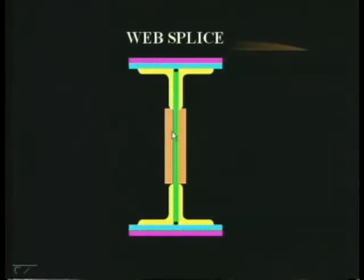We have to search for a section where the stress is less, and at such a point we make the joint using these small plates. These are called splices, and because these splices are used for web plates, it is called a web splice.